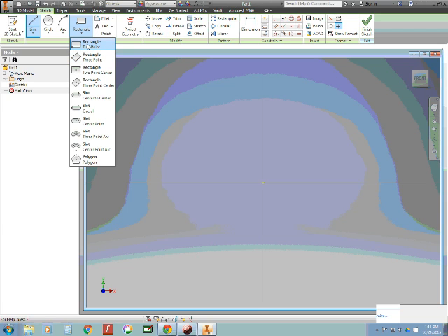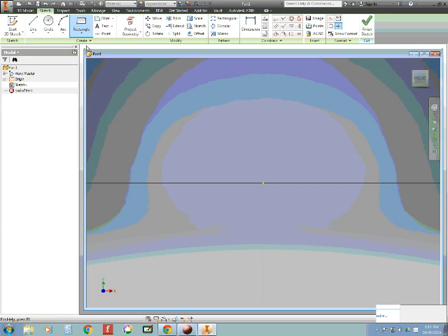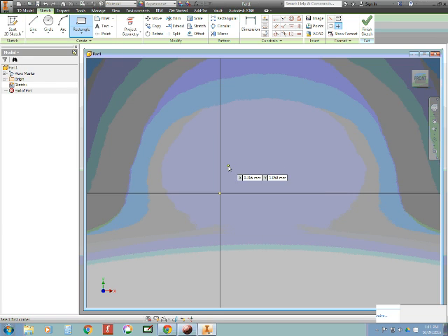So this is the one we're going to choose. But again, when you have time, come in here and play with some of these. So we're going to choose a 2-point rectangle. And when you draw this, I'm just going to throw this on here. The width is 31.8. And then if you hit the tab key, it'll go to the next box. And this was 9.6, I believe. And then press the enter key.